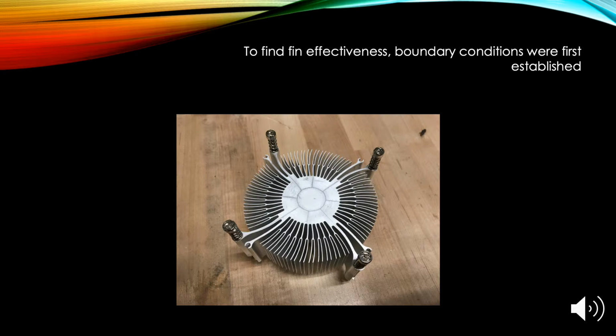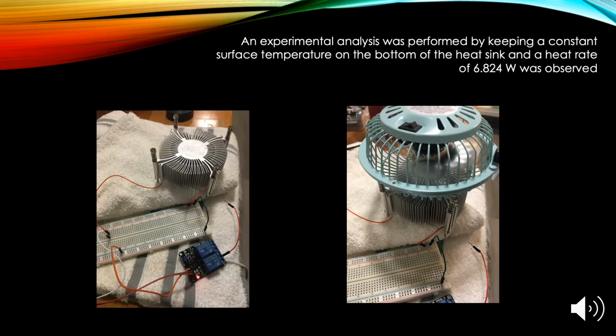And plugging this back in, I got a Biot number of 3 thousandths, which signified that this was an appropriate approximation. In order to get a free stream temperature, I recorded the room temperature atmosphere, and that was 23.22 degrees Celsius. I also picked a base value for the fin, and that I established at 37.78 degrees Celsius.